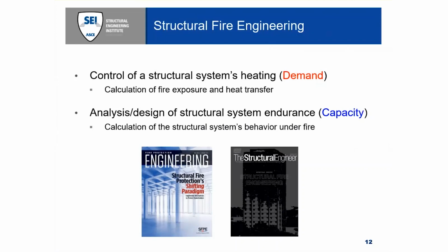So we can't rely on sprinklers, which I'll get to. Also, the ability of a structural system to endure fire effects can be enhanced with specific member sizing, connection and reinforcement detailing, or other means to provide added structural robustness.